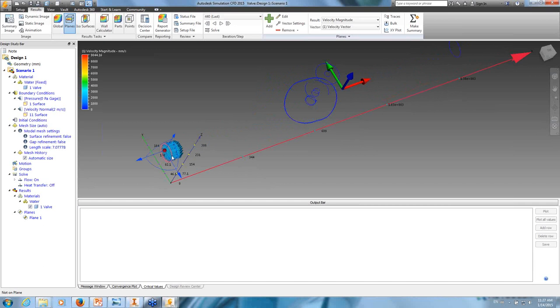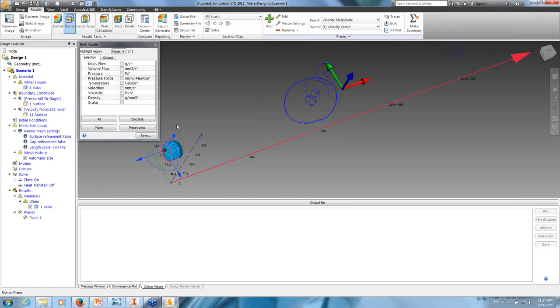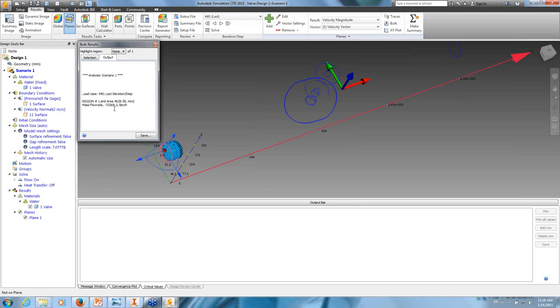So now I aligned it to the inlet, where I can use the bulk calculator to, let's say, calculate the mass flow in whatever units I want, let's say pound per hour. And if I click calculate, it's going to give me that value, how many pound mass per hour. I can request any of those output results. In the next example, since we have temperature as well, it'll be more interesting to see what kind of results this bulk calculator gives me.